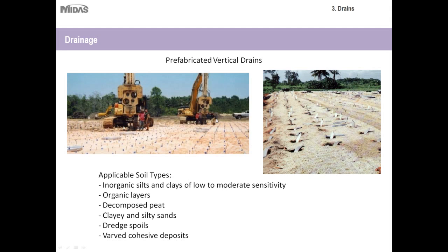Just keep in mind that when you're doing any consolidation analysis, or designing a consolidation project, typically you'll be involved in analyzing and designing the drain spacing, which we'll discuss at the latter end of this chapter. Whenever you have a large project site that consists of very saturated clay, it's very common to do a draining period first before actually building your structure on the site.